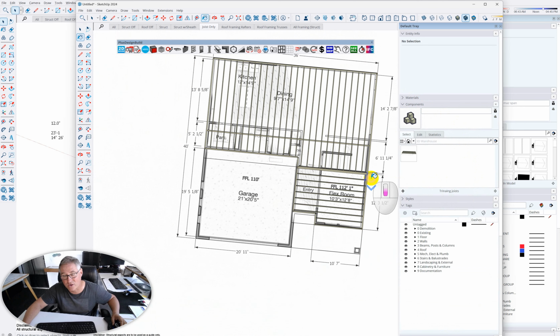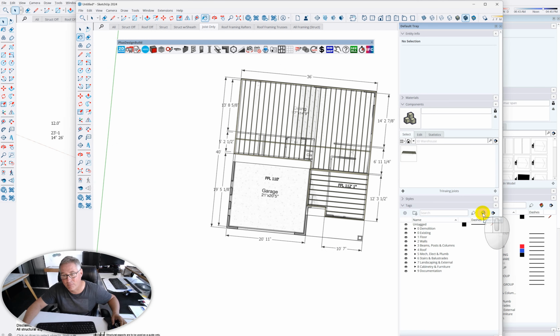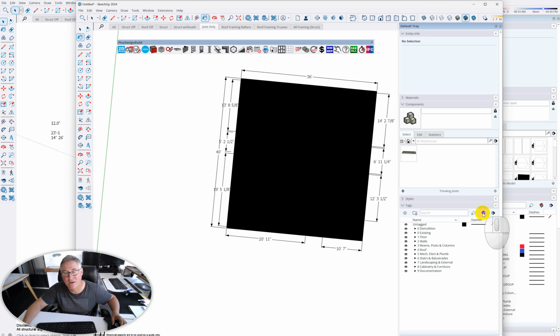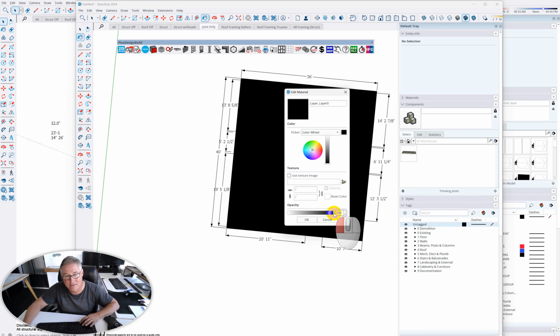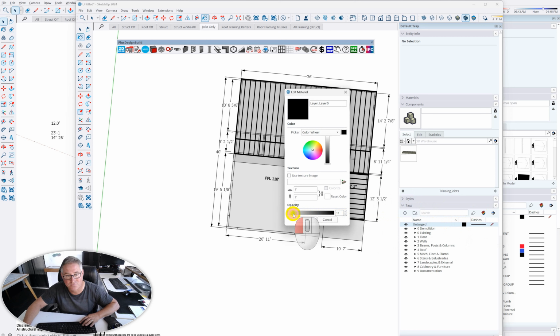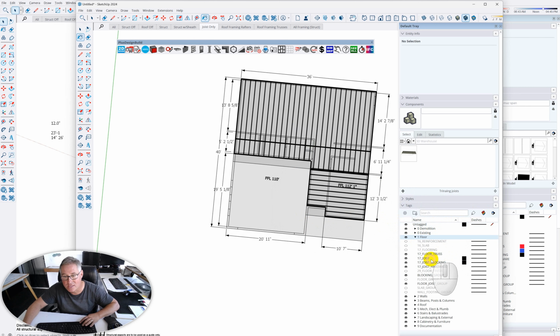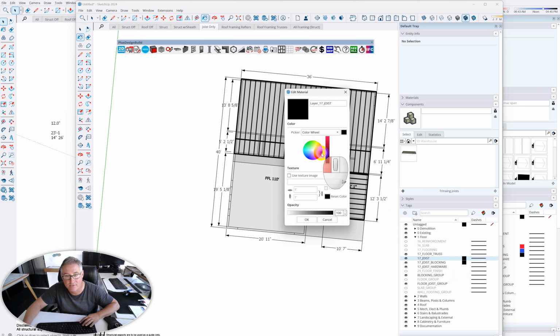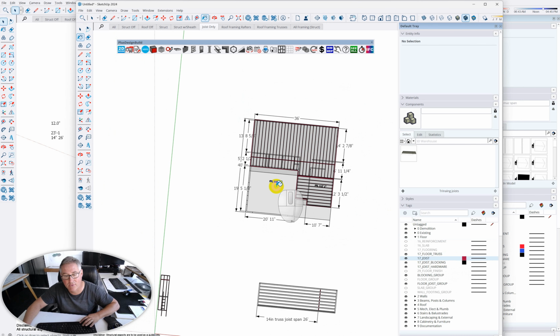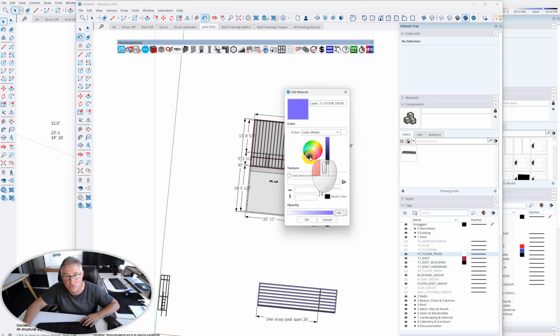It is a good way to create templates, and that is color by tag here. Right? What happened was that anything that was untagged is now black, which means I can do one of two things. I can change the color of that tag to opaque. And then if I went to my flooring, you'll notice it's pretty organized. My floor joist, which are solid, I can change them to red. Here, go okay. However, I've got truss joists. You notice down here they're white. If I went to floor trusses and I want to change them to blue,